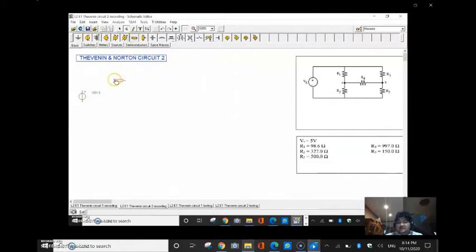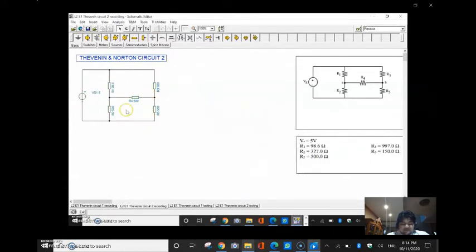Again, we will use another circuit to prove this theory, using a parallel circuit with 5 resistors. For R1 to R4, we will be using the same values, but with R5 at 150 ohms, with the same DC supplied voltage of 5 volts. We will then run again the DC analysis with the table of DC results.